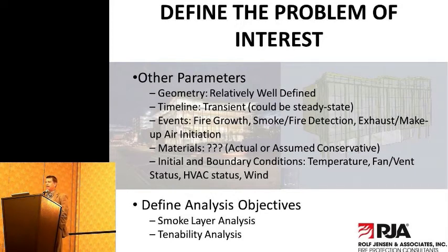Usually we're doing this type of analysis fairly early on in design because it's a big piece of how we're going to establish the smoke control. It has an impact on where the mechanical is going to put their vents, their fans, all sorts of things that could impact the actual design of the building. When we talk about smoke control, experience tells us that it's usually not about the exhaust. You can put as big of fans as you want on the roof for the most part. That's not the big issue. It's the makeup air. How are we going to get effective makeup air into the space at relatively slow speeds, which is required by codes, and we don't want to impact the smoke plume, the fire plume, and so forth. And so it can have a rather large impact on the design of the building.